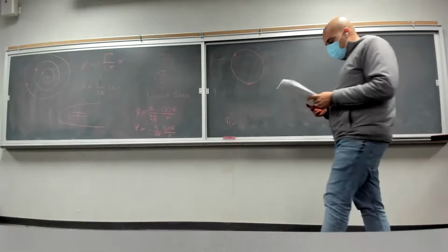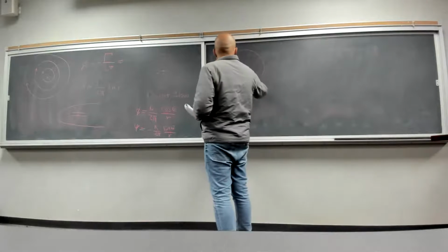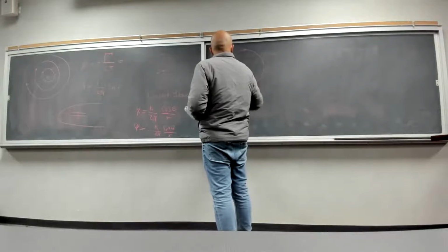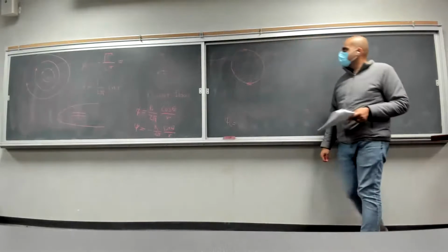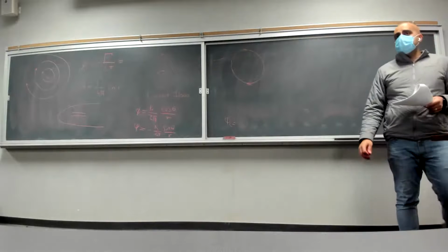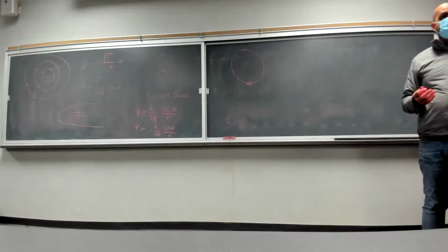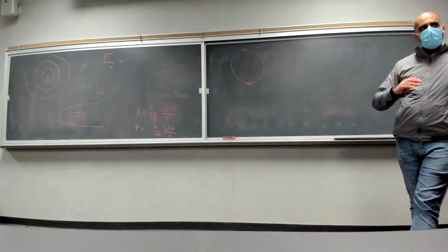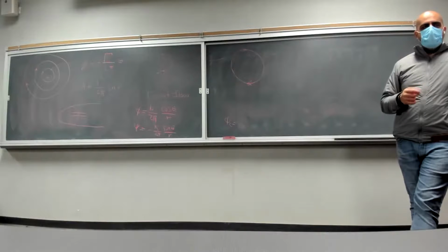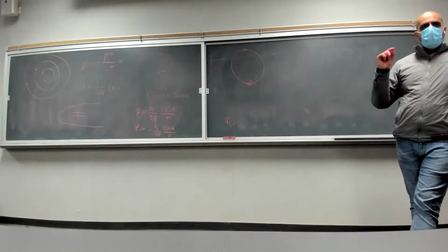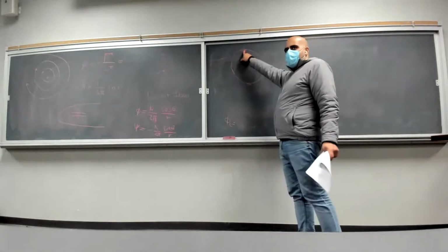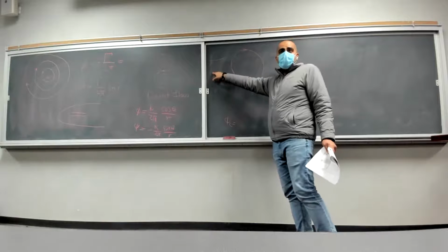How do you think the flow would look like? Let's do the direction of rotation in this. This is the uniform flow plus the vortex flow that we saw, right? Which essentially means that we are moving the stagnation points, right? Because the velocity at one side, at the top of it, is going to be higher because it's being added to the uniform flow.